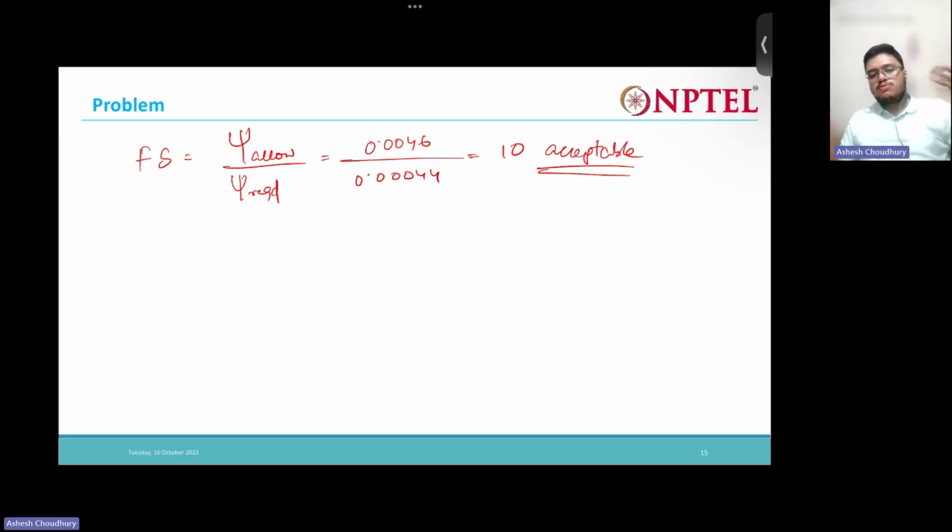So this is the cross-plane permittivity, right? This means the geotextile will be able to allow the water to pass through it adequately. I hope you understand. This is a little critical. Here we have a geotextile placed like this. This is the high level, this is the low level.